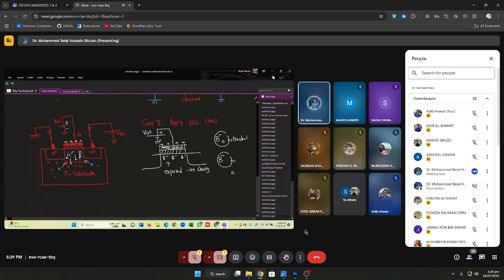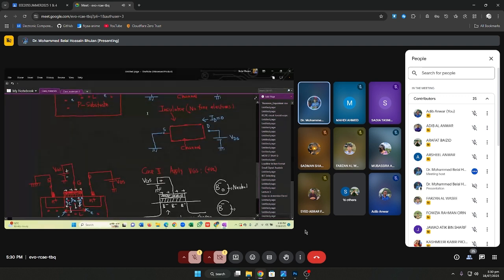So we find electrons accumulated underneath the oxide layer. This positive charge on the metal pushes the holes downward, so we get a depletion of holes by exposing negative charge. At the same time, it attracts electrons towards the interface, so we have a layer of negative charge. Now imagine this scenario. So I draw these things again here.